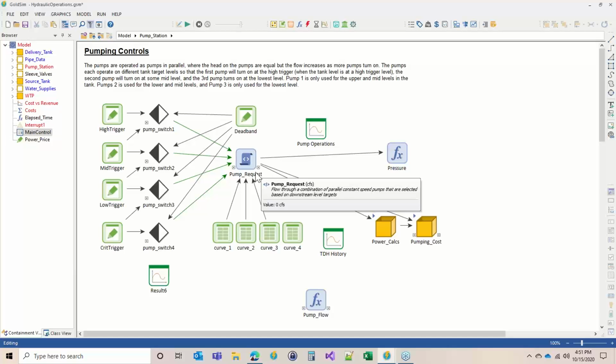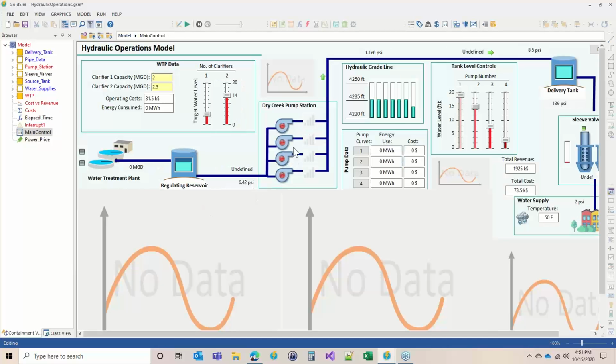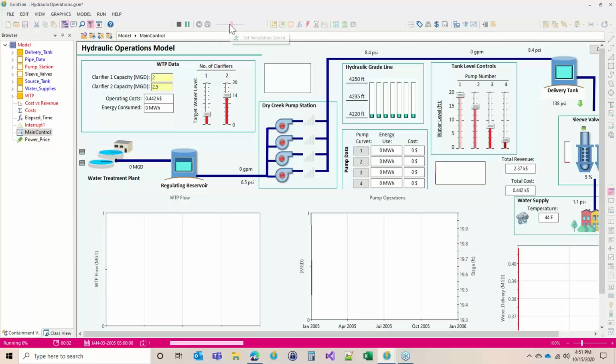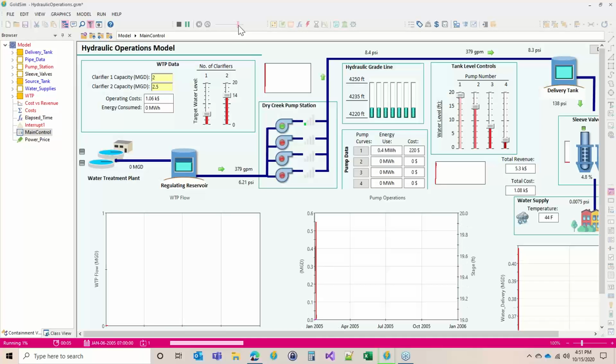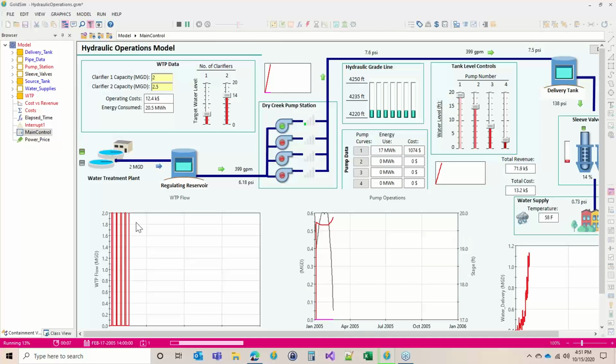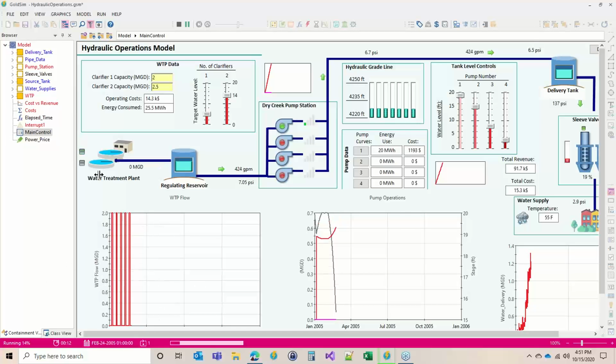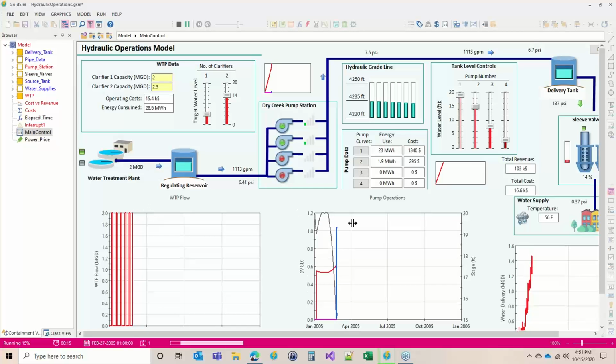You're just multiplying here, and then you can calculate things like friction losses in a pipeline, and that's what this is doing. Anyway, when you run this kind of model, it's maybe more interesting to run in slow motion. Maybe not quite that slow. Anyway, what it's doing is showing you, at various places, the flow coming from the treatment plant. And here, this shows you the ongoing status of the pumps. These are both pumping at a pretty low rate right now.